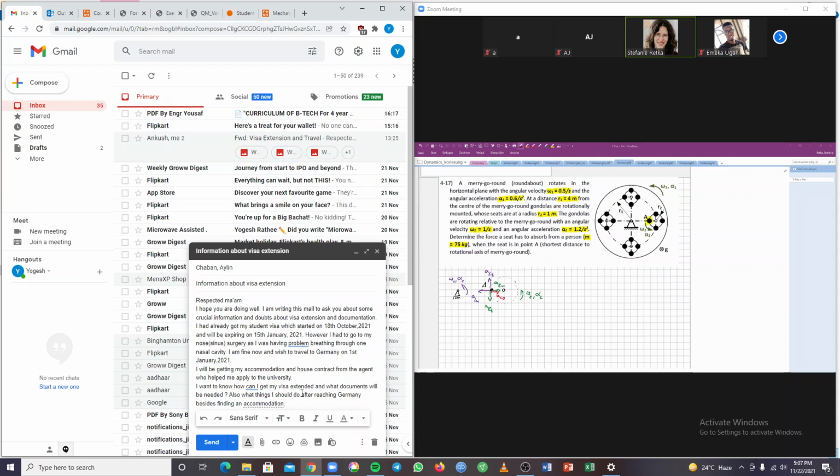Maybe you just write it down to remember how it works. Your thumb of the right hand corresponds to the axis of rotation of the leading motion. So in our situation, it points upwards, out of the plane of the paper. Then the index finger indicates the direction of the relative velocity. The relative velocity points in the same direction as the tangential component of the relative acceleration, downwards in our case. Then the middle finger indicates the direction of the Coriolis acceleration, which shows the direction as in the diagram.